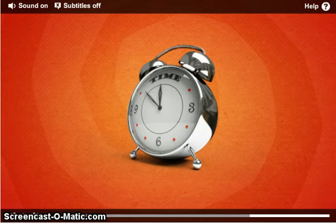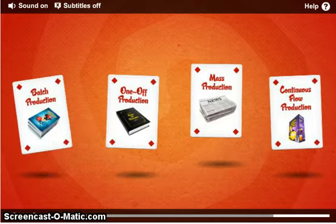There's also an approach called just-in-time production. This is not a type of production method on its own, but it's an approach that is used with batch, mass, or continuous production. It means buying raw materials so that they arrive in the factory only when they're needed. This saves money because manufacturers only need to buy enough materials to cope with current demand and don't end up with a store crammed full of materials.